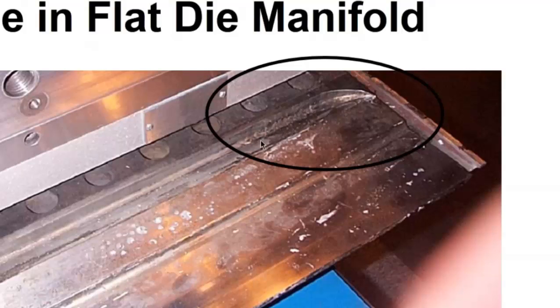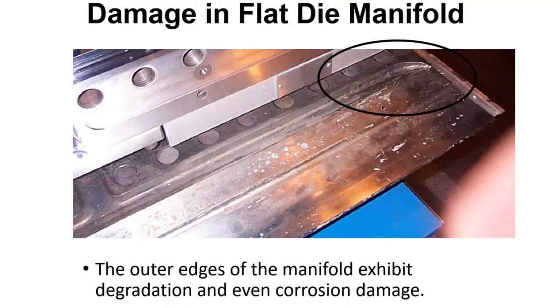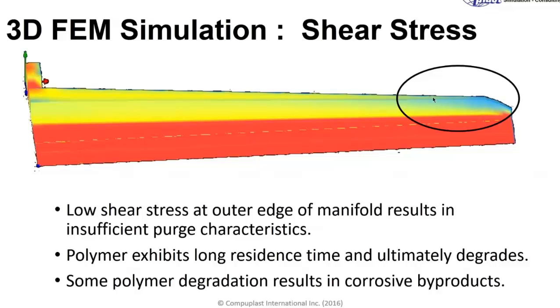And what we do is we simulate the flow conditions in this geometry, and we look at the shear stress on the surface. And once we have the shear stress values along the surface, we go back to the geometry and we measure back from the edge. Let's call it 3 inches from the end is where the pitting starts to occur. So everything is good in this channel, all along here, and just about this area right here, we start to get the pitting. And then we go back to our simulation and we measure the same distance back from here, and we pick off a value of shear stress.